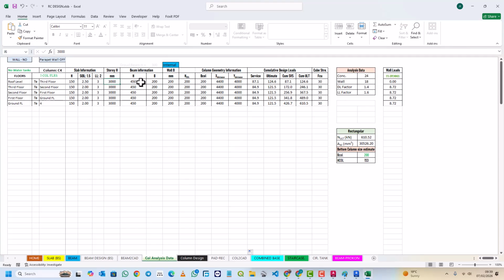Okay, so this floor, we can put here 0 like that. Yes, that one is okay because we don't want the wall load here. The first floor actually we don't have it like that. So after this you do your sizing. As I said, the sizing you can assume one size as 200. Then this other one will just come. Otherwise, if you want to do a square, you just square root. So here we are getting 200 by 136, which does not make sense. So we'll just go with a column of 200 by 200.